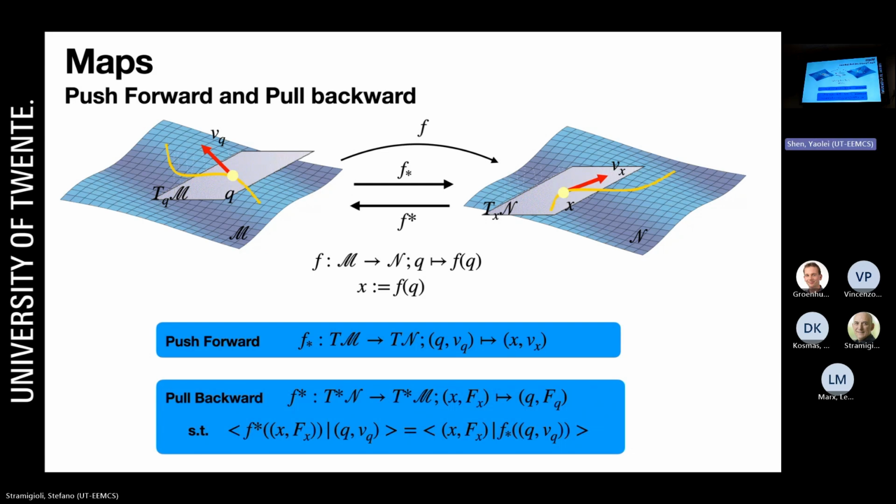And then they are joined. When we did linear algebra, we said if you have two vector spaces, which are these two vector spaces at this point, Q and X, if there is a map, there is always a map in the opposite direction of the dual spaces. So if you have the velocity maps like this, then you have a map of the force in the opposite direction.